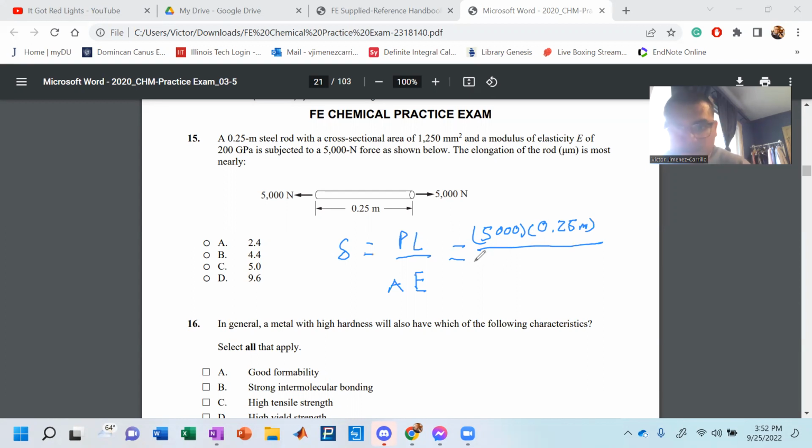which you can convert. So I'm just going to put the giant conversion factor here. For every meter, it's 1,000 millimeters. Got to square it because everything's squared down there. And then gigapascals are just 200 gigapascals, but you need to make sure they're in pascals. So it's 10 to the 9th pascals for every 1 gigapascal.